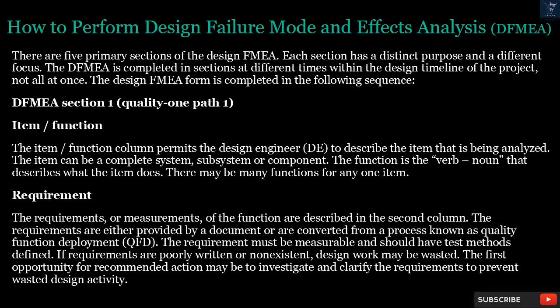Item/function. The item/function column permits the design engineer to describe the item that is being analyzed. The item can be a complete system, subsystem, or component. The function is the verb, noun that describes what the item does. There may be many functions for any one item.